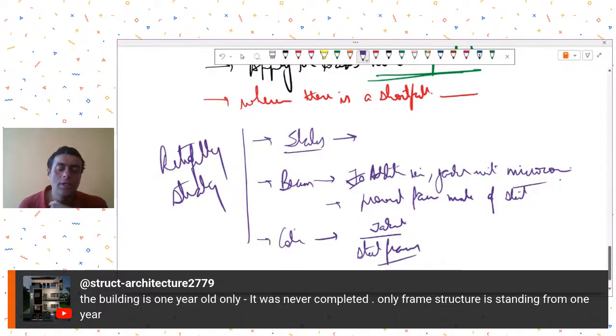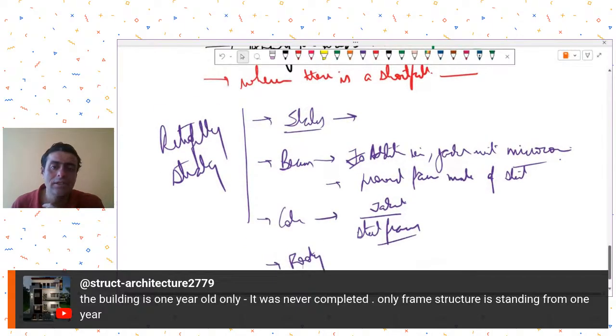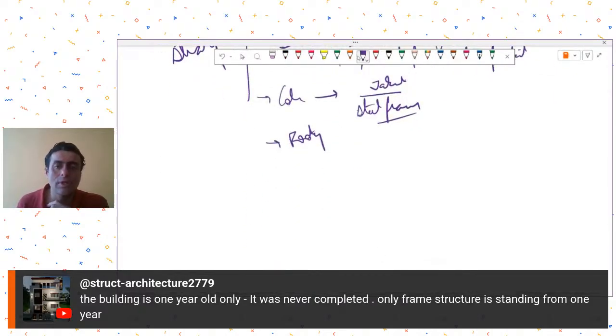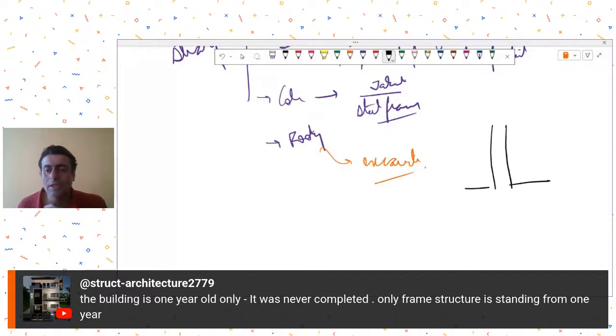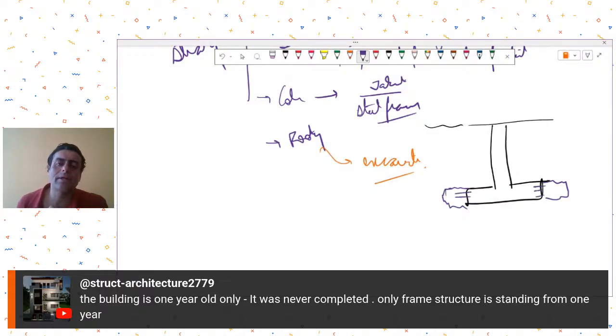Now, if footings are a problem, that means if footings need resizing, there is a possibility that your footings may also require increased sizing. Then it becomes tricky because then you will have to excavate and then increase the footing size. So over here, one of the ways could be that let's say this is the existing footing. First of all, you will have to excavate, and one of the options is, if possible, you may increase the plan area in this manner. That means by rebarring over here, but this is practically difficult to do.